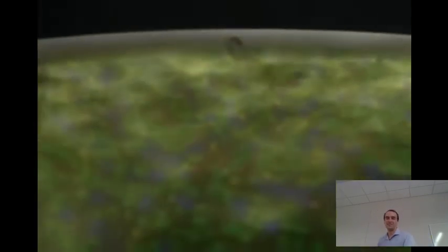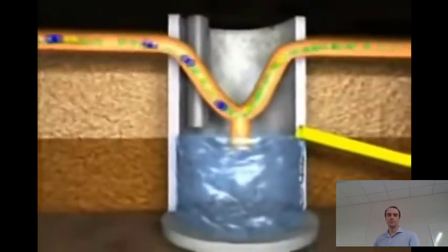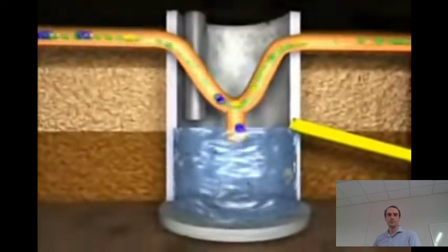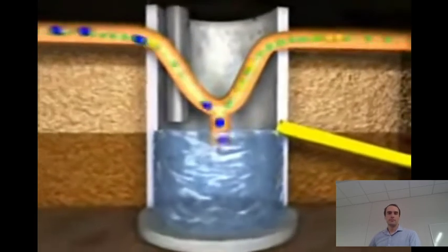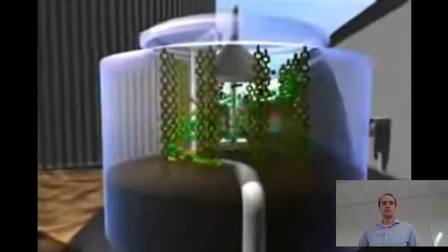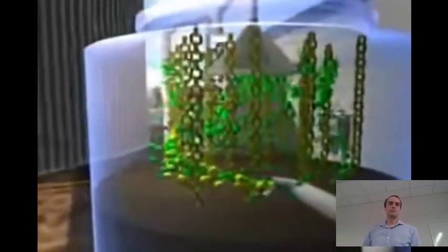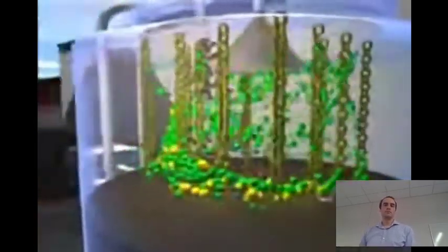As water vapor and hydrogen sulfide are problematic for the utilization of the gas later, it is necessary to treat the biogas now. The gas is first freed from water vapor, colored blue here. The condensation water is collected in a condensation shaft and pumped out. The aggressive trace gas hydrogen sulfide is now extracted from the biogas in a biological desulfurization plant.